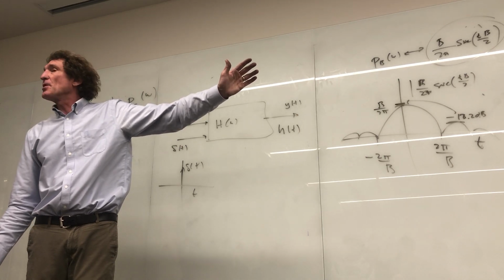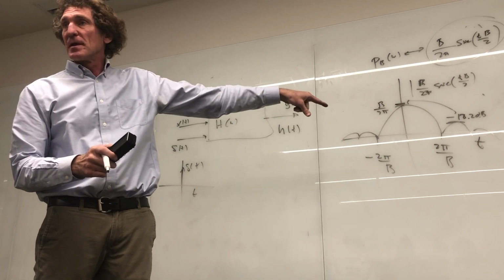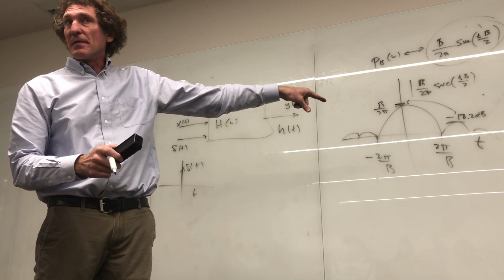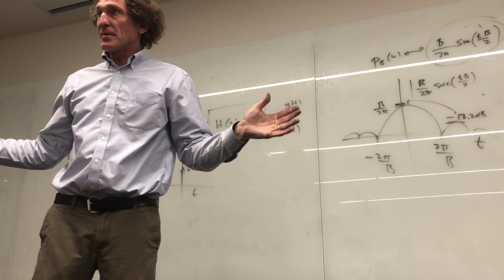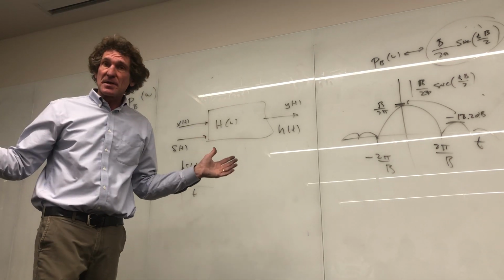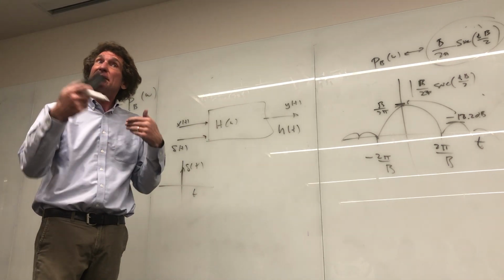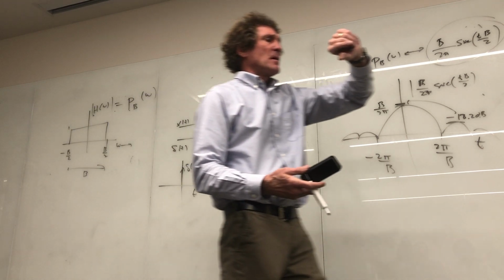You follow me? But if you don't have a data record, if it's real-time data processing, you can't build that thing. It's non-causal. Got me on that one? This filtering is used extensively for recorded data, but it is an impossible filter to actually build in real time because it has to anticipate that something's going to happen. And it's impossible.